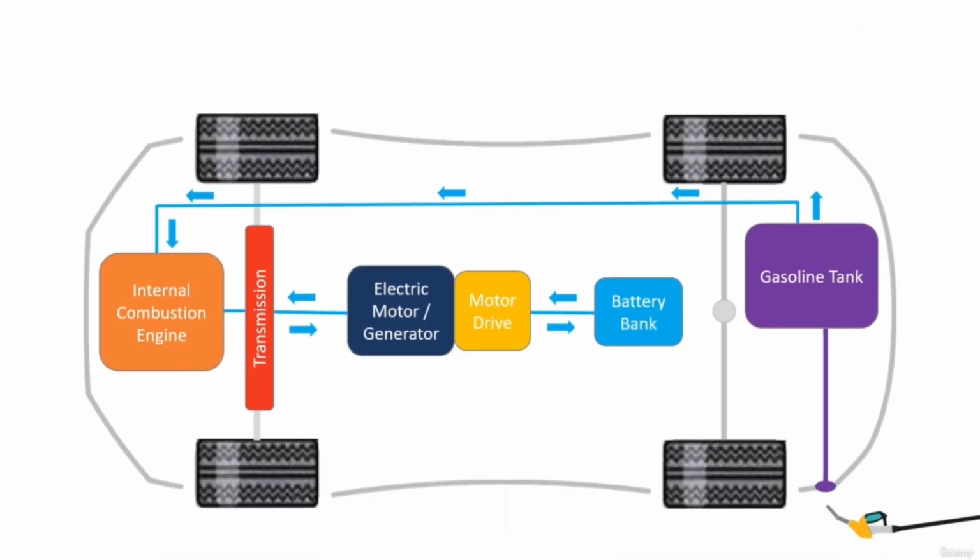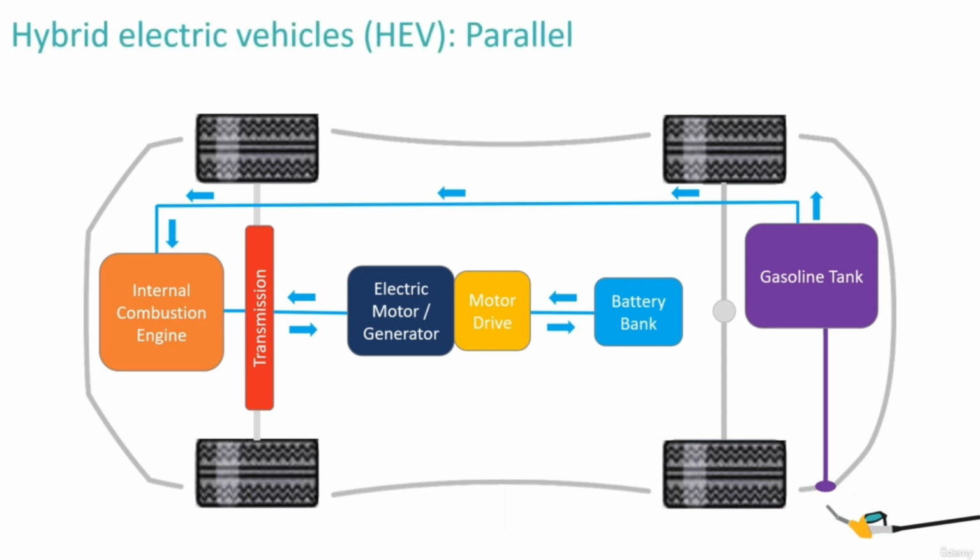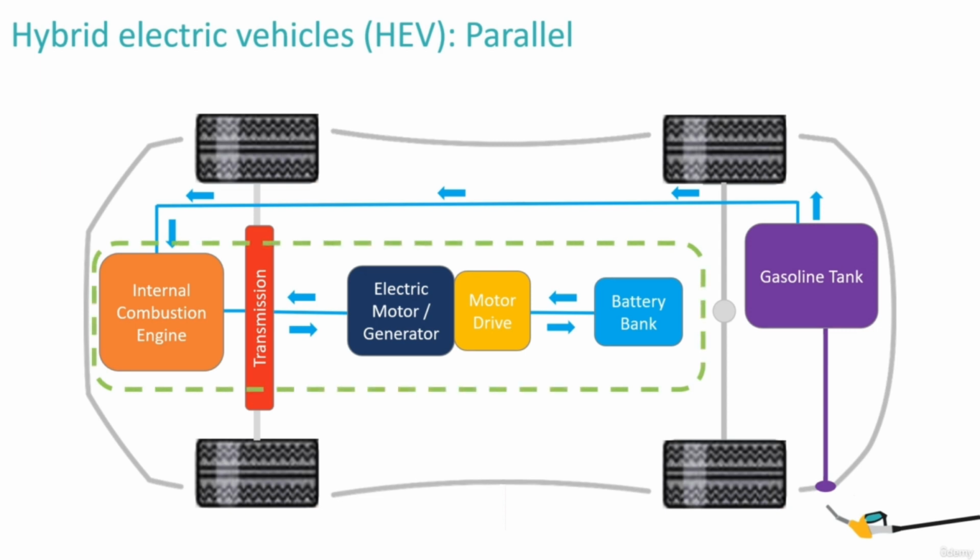Hybrid electric vehicles are powered by internal combustion engine as well. However, in addition, an electric motor can propel the vehicle by using energy stored in the batteries. The battery is in turn charged by drawing energy from the engine by using the electric motor as an electric generator. To operate the motor and generator mode, a clever power electronic motor drive is used. The extra power provided by the electric motor allows for smaller engine. Further, the motor allows the engine to be operated in its optimal efficiency point, resulting in better fuel economy.